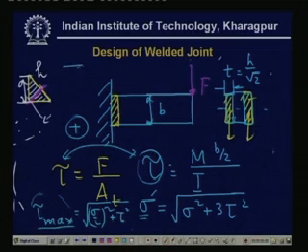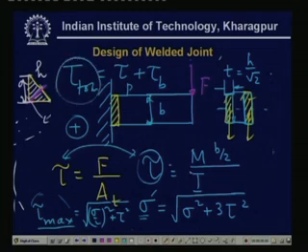So, the total stress, tau total, is tau direct, that is primary, plus tau due to bending. Then we can use this formula. Now, here we see that the factor of safety is a little larger if we consider this. Therefore, this is much used, and this is mostly used in Soviet Russia and many other countries, but this gives a conservative value.